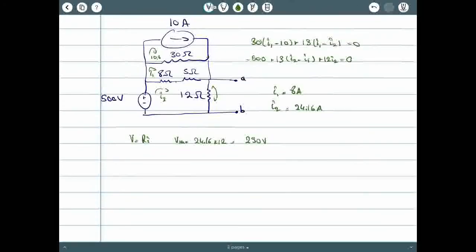Now to find R Thèvenin is much easier. We just set all the independent sources to 0. Take it as a rule: a current source is an open circuit, and a voltage source is a short circuit.